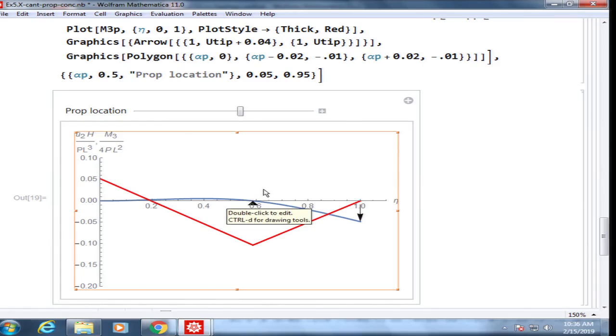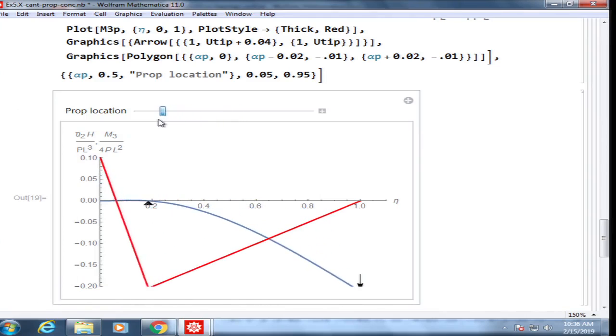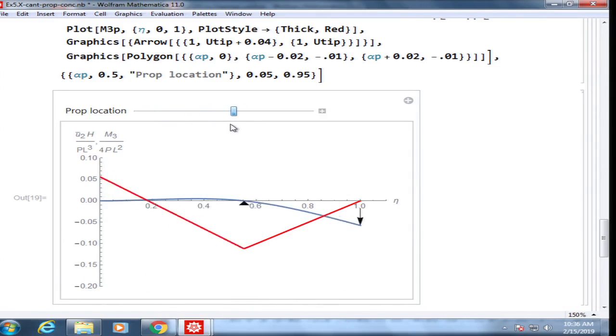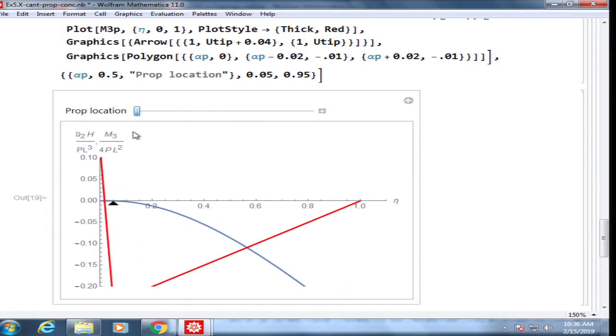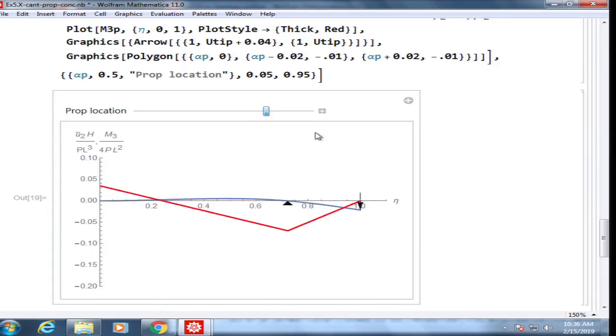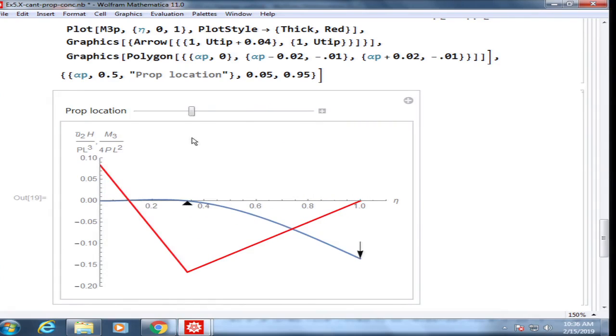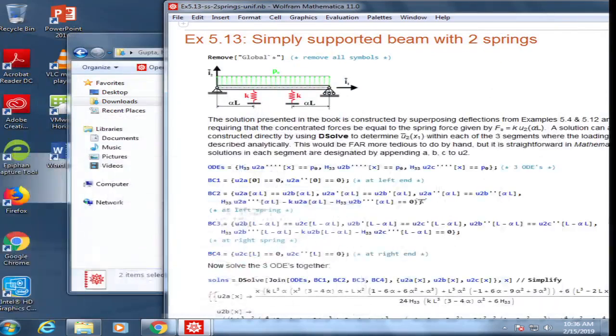So when you're designing something like this and you want to restrict the displacement caused by P, you will think of a method like this and put a support in the middle, right? So by doing an analysis like this, you can see that if you put a support anywhere in this region, it's a significant reduction in displacement, right? By just putting a support at, let's say, 0.5, you can get a significant amount of reduction in displacement, and then there is not much benefit. So all this analysis can be studied with any solver like Mathematica. But let's move on to another problem.